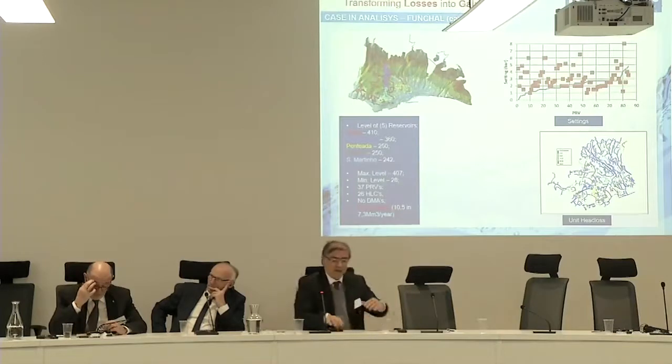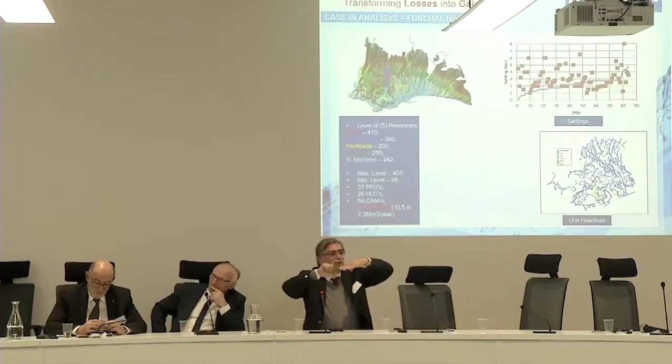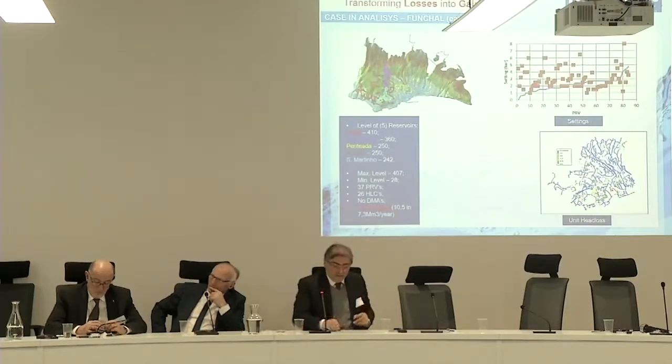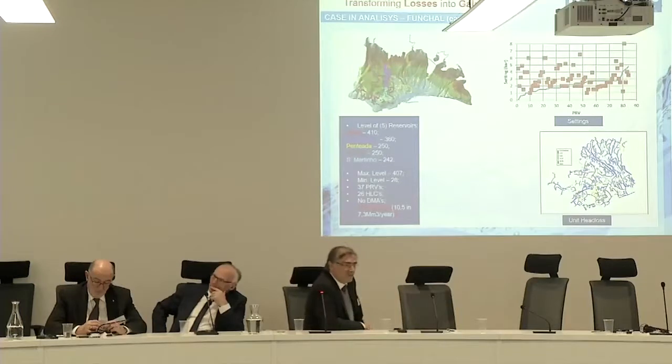So if you have a problem of low energy here, and you have the energy line like this, and you build a building like this, what do they do? Get the pressure up. But the problem was not the valve. The problem was the pipe, which has a great head loss. So they don't solve the problem. They came with a scheme to solve.